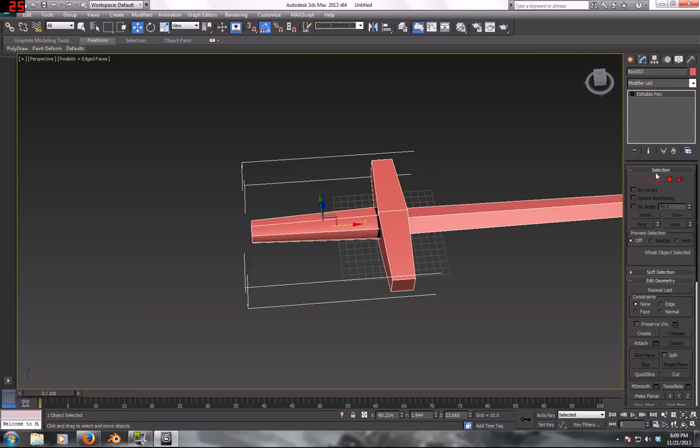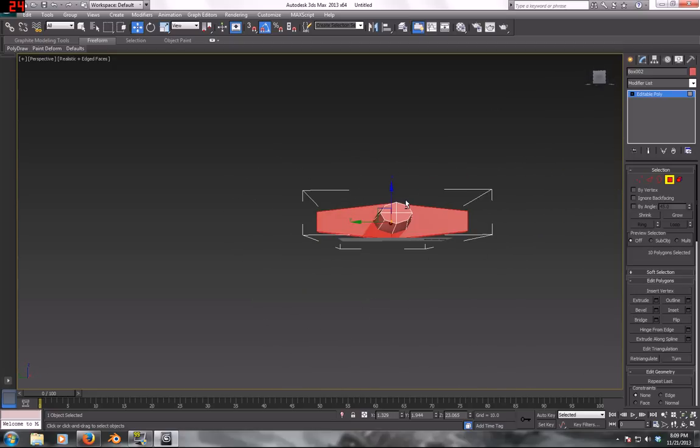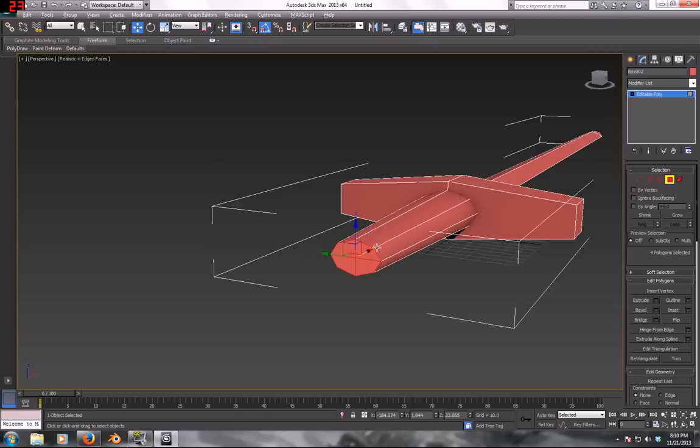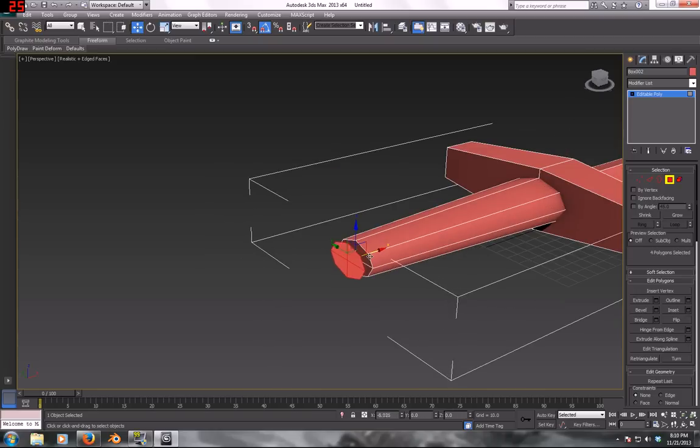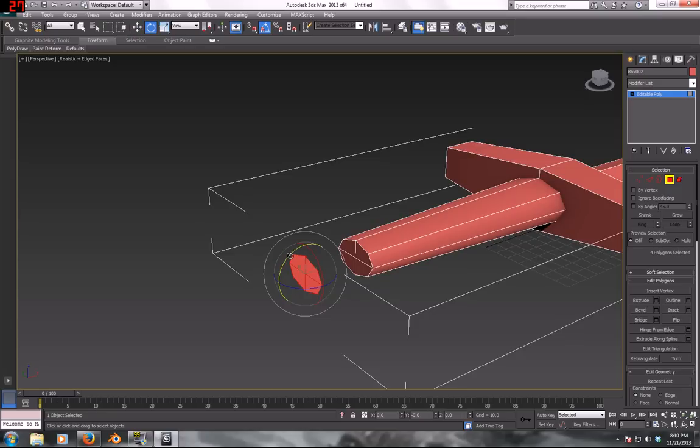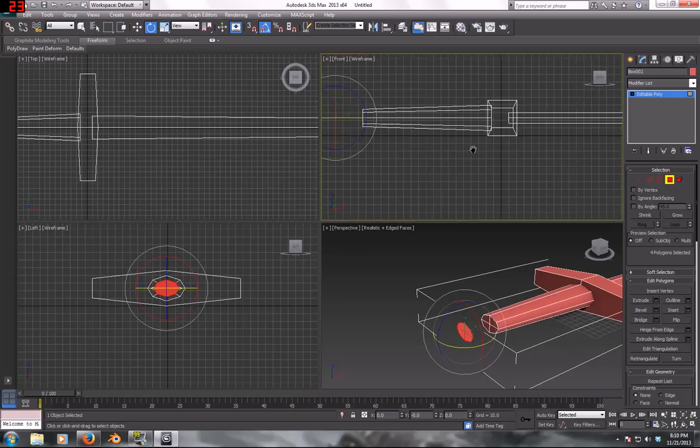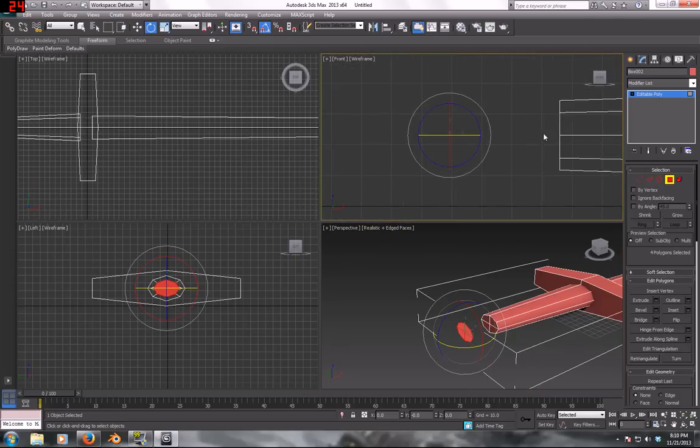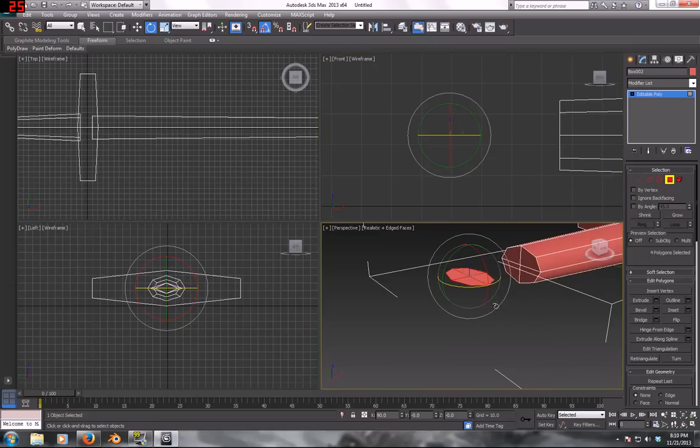Now how do I want to do the, whatchamacallit, the pommel. I'm going to pull out these faces, clone to element, that's shift and dragging once you have them selected. Then I'm going to hit A, which toggles the angle snap, and that'll make it snap to 5-degree rotations. Alt W so that I can see it at this side again, and there we go, rotate it 90 degrees.